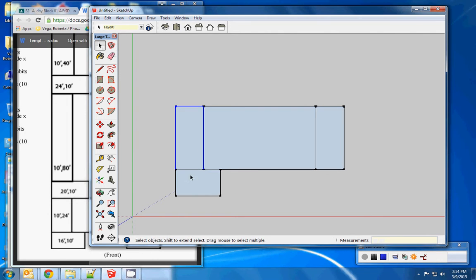And again, I'm going to choose that rectangle, hold my Control key down, use the Move tool, and grab this rectangle by the corner and pull a copy directly across so it exactly lines up with the other side.